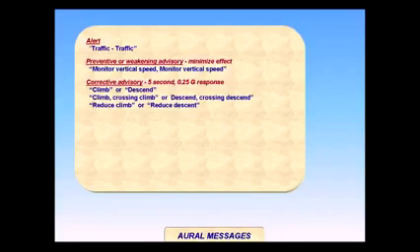"Climb, crossing, climb. Climb, crossing, climb." Or "descend, crossing, descend. Descend, crossing, descend." Set vertical speed to that shown in green on the VSI tape and avoid the red prohibited area. You will cross the threat aircraft's altitude.